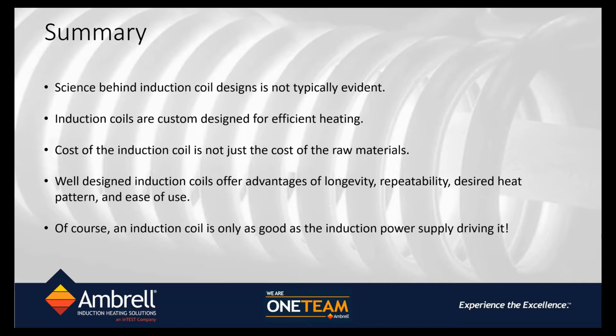However, there are a lot of applications, like in the heat treating industry, where there are such high currents flowing through copper coils that it leads to the fatigue of the copper tubing, which means that the constant on and off of the induction heating coil basically fatigues the copper, and the copper gives because of this repeated on and off of the induction heat process.